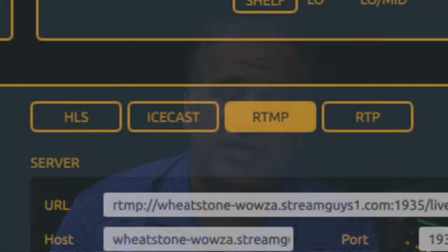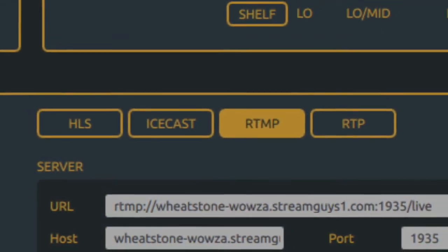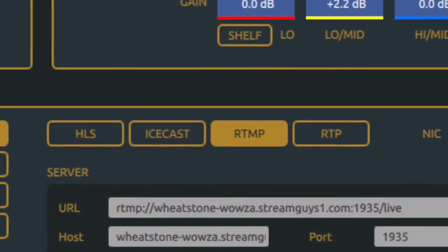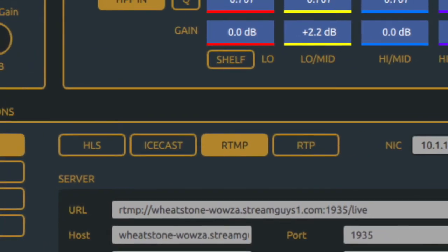So both products have up to 8 individual processed streams. Each of those streams can have one or up to 4 outputs per stream. So really you can have a total of 32 output streams. And we say that it accepts native WheatNet IP or any analog or digital input, as well as any drivers that you may be using. We are able to have cloud-ready, compatible standard CDN and streaming platforms like HLS, IceCast, RTMP, and RTP streaming.